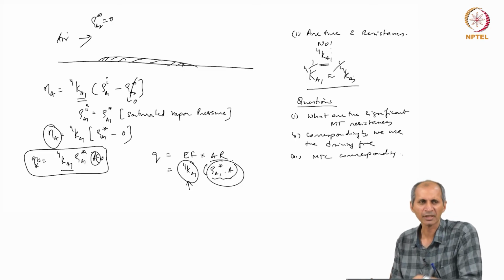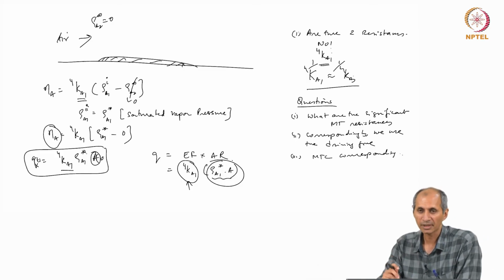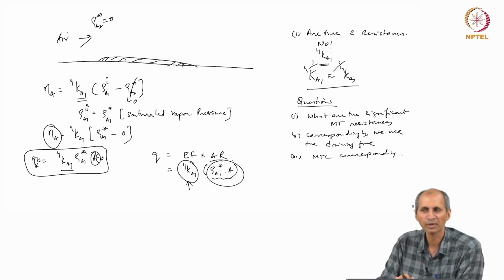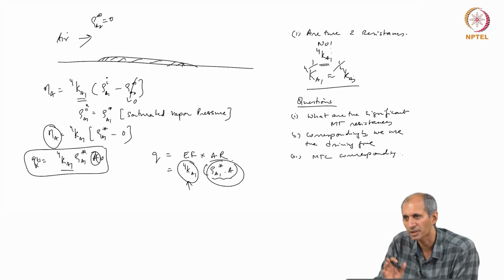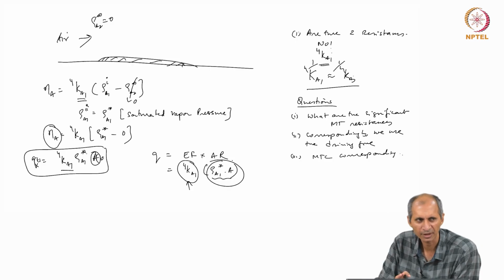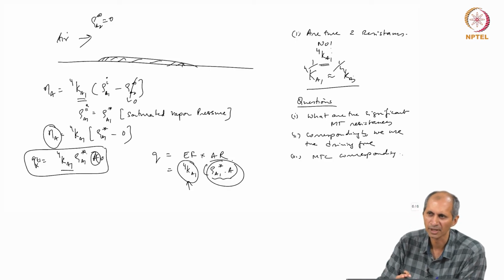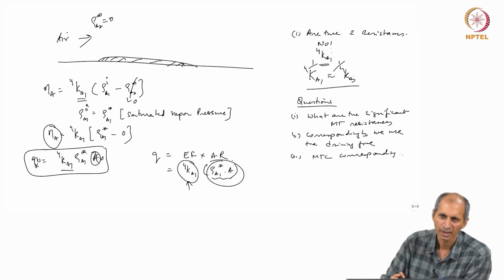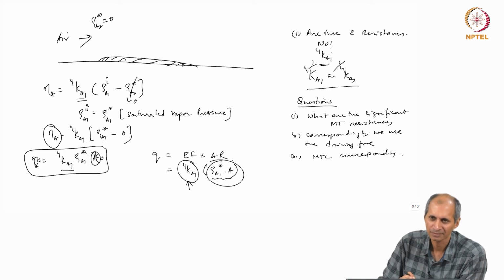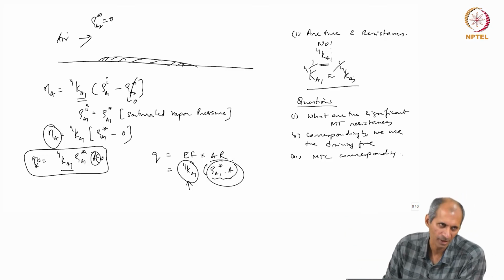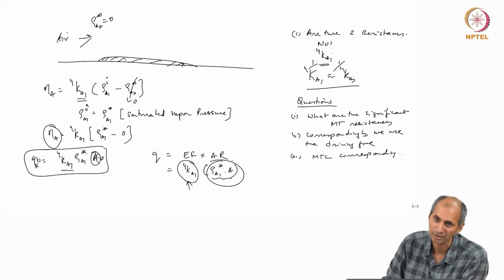A lot of times the biggest challenge is to select the correlation for the mass transfer coefficient, because you will not find an exact correlation for whatever you are looking for. You have to find an equivalent correlation which is the closest. So, these are all estimates. There are so many assumptions in these kind of studies. The more complicated studies take longer to solve, and so many of these things come under emergency response. Suppose there is a spill, how quickly can you tell people that concentration is going to be this much at a distance of 5 kilometers or 2 kilometers?